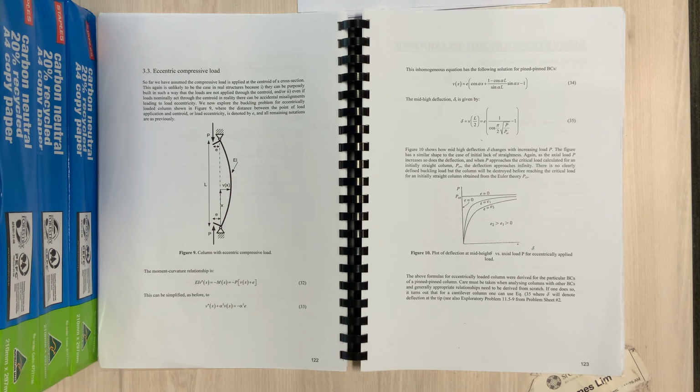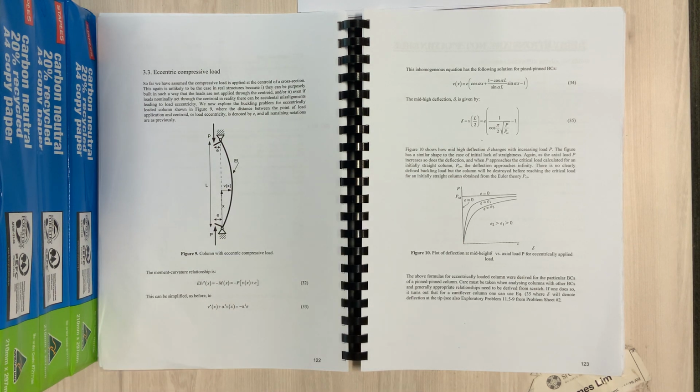So we talked about before, there's no such thing as an absolutely perfect column, and a real column is going to have geometrical nonlinearities, imperfections, residual stresses, and the material properties are not going to be the same in all these directions. As engineers, we just need a pragmatic way to deal with all of these problems. Putting that aside, you've also got the issue of how to actually apply the load, or where the load is applied.